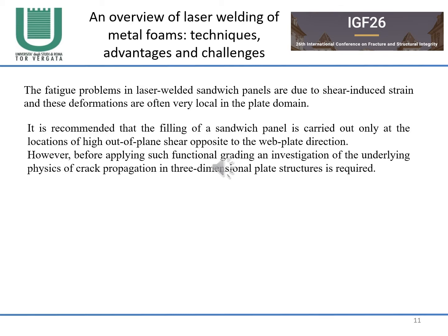The fatigue problems in laser welded sandwich panels are due to shear-induced strain, and these deformations are often very local in the plate domain. It is recommended that the filling of the sandwich panel is carried out only at the location of the out-of-plane shear opposite to the web plate direction. However, before applying such functional grading, an investigation on the underlying physics of crack propagation in three-dimensional plate structure is required.